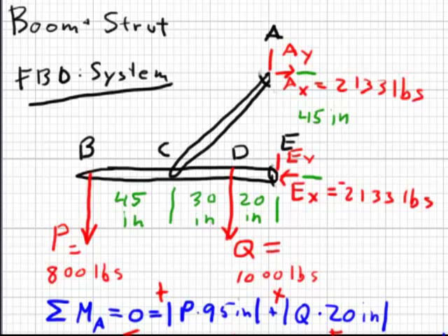Well, what does this mean? This means with the loads that we have here, and AY taking the load that it is, EY must actually be pushing down at point E to keep boom BCDE in balance about point C. So we'll put the arrow here and this arrow here and fill in our chart. AY is 1,920 pounds and EY is negative 120 pounds.